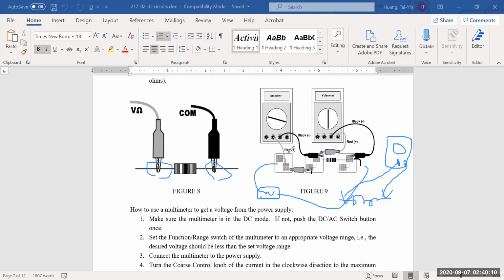Okay. Now, when you want to measure current, you want to insert an ammeter in the circuit, so you need to break the circuit. Here we take this resistor out of the spring, so it is not connected to the spring, and then you have the positive here, the ammeter, connected to this one lead, and the other one is connected to this.